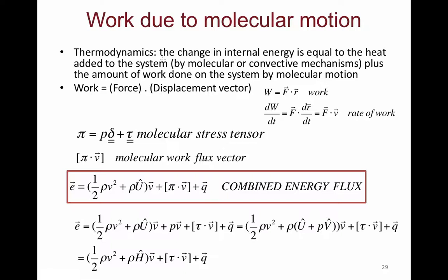So we don't have external forces or any kind of generation within the volume other than that from the friction and the work of the molecular forces. So that's not a source in itself, right? There are no other sources. So basically, the net rate of E in and out is equal to 0, that is my shell balance. And this is Ex. It technically has a Y component that we're ignoring, right?